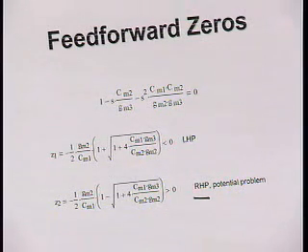We could unilateralize the feedback. We could put a follower. We could use cascode devices to try to avoid having a feed-forward path. If we eliminate the feed-forward path, we know we also eliminate the zeros. All the same trade-offs that we discussed before apply here. You put a follower, you reduce the swing. So you have to be careful. In the notes, there are a couple of design examples.